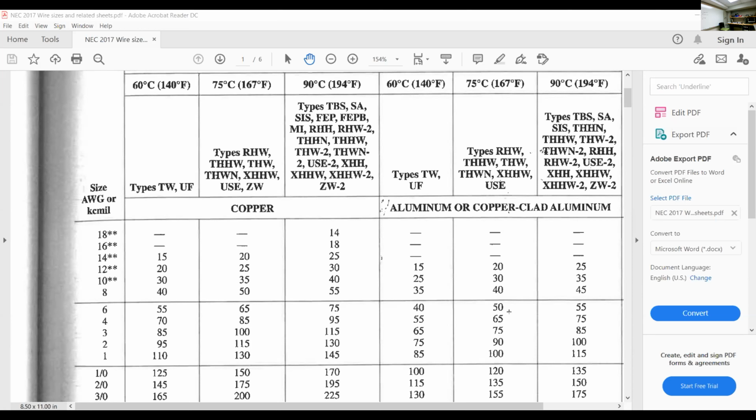That stuff will be stamped on whatever device it is in most cases. I'm going to pass this around. And you can see where it tells you, way over here, it says for your wire connections, anywhere from the number 10 to 18, CU, and that's copper, 75 degrees Celsius. And that's the rating of the terminal. That's the limitation, but you see that.